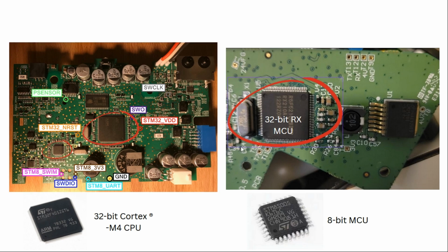On that smaller auxiliary board, we have another microcontroller, this 32-bit RX MCU, which interacts with the modem chip, which does a lot of the teleservices for sending data to both your doctor and the ResMed app. So this, in a way, also acts as an auxiliary microcontroller, offloading a lot of that heavy work from the main microcontroller unit and just sending the data over to that instead.